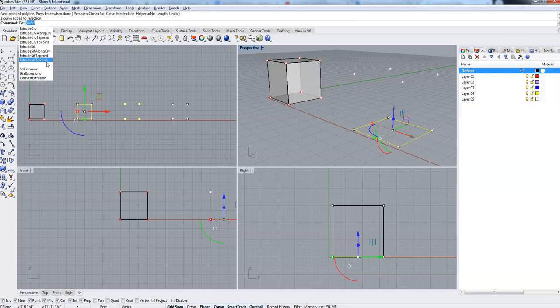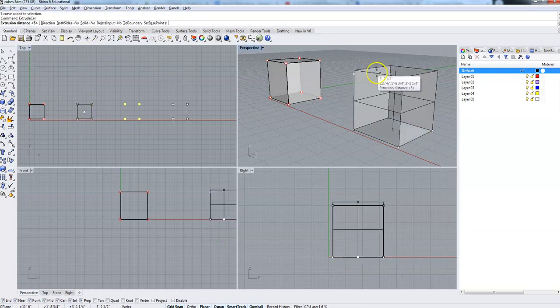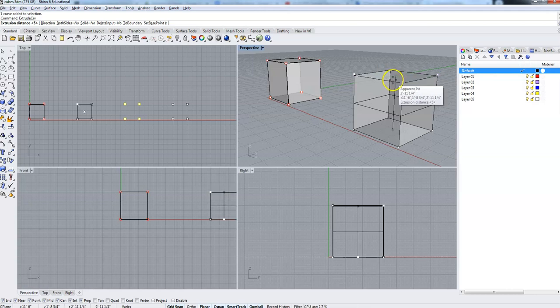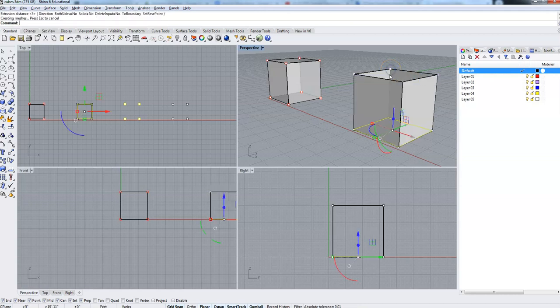So Extrude, and then it comes up as the top option, and you can see that it immediately wants to get into action. We can just mouse over one of those points, and that's another reason why I like starting with the points, because it creates an anchor point for us to mouse over, and it knows to stop at that point. And so we can click that.